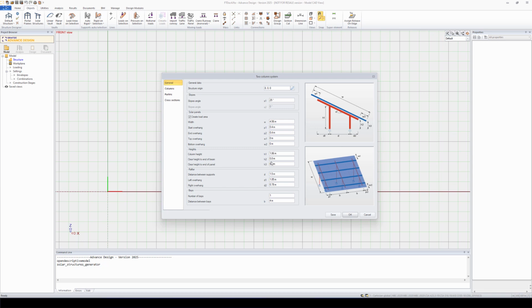As I mentioned earlier, it's going to automatically adjust the parameters. For the rafters, I'm going to use 2.5 meters. Just to let you know, in this scenario I am using metric units, but you can also change the units in Advanced Design to imperial. It's very simple: you just double click here, and then you can switch all of the units to imperial units. Again, after I put this in, it's going to automatically calculate the other D1 and D2 spaces, or the dimensions there.